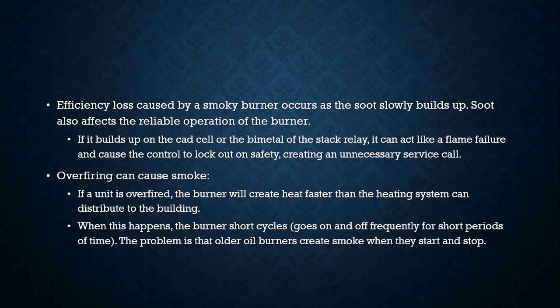If you still have a stack relay, which is a temperature operated safety control, and soot builds up on the bimetal of that, it acts as an insulator. It's not going to pick up the temperature correctly. It's going to cause problems. It's going to cause things to lock out unsafely. We have to make sure these things are working the way they're supposed to.